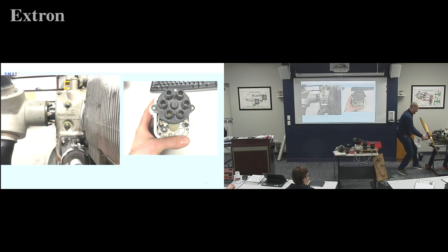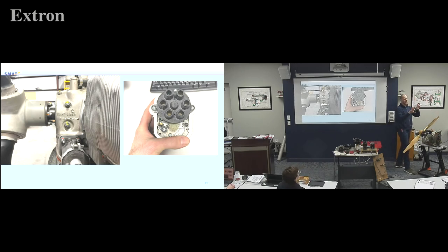I had it all connected where it was happy. There. I don't have all the gears on here that you will on your engine, but you've got a gear case. Your magneto basically is going to plug into the back of here, and one of those gears is going to drive it. So it just happens to be where it's living, how they geared it. It's going to have to go one way or the other, and we didn't decide to engineer them all to go one direction, so it's just how it lives on there. If you go much deeper, we get way off in the weeds, because most of our engines run counterclockwise, but every once in a while, you get one that runs clockwise, and so you just got to know what's stamped on the side of it.